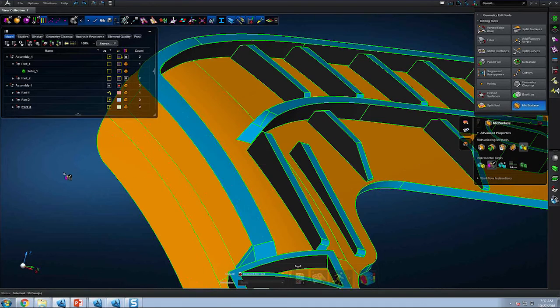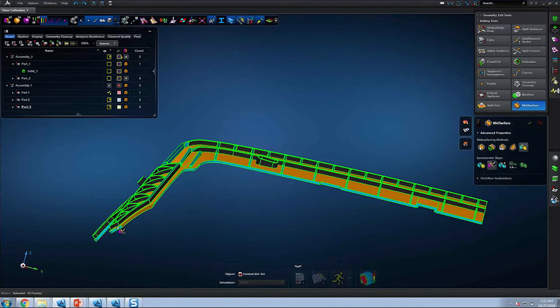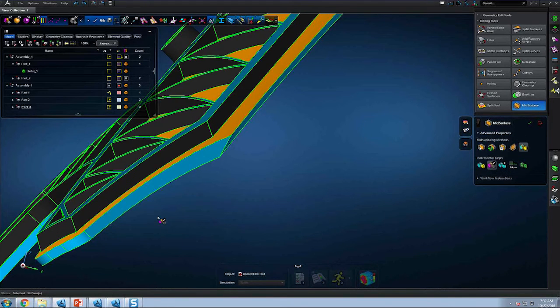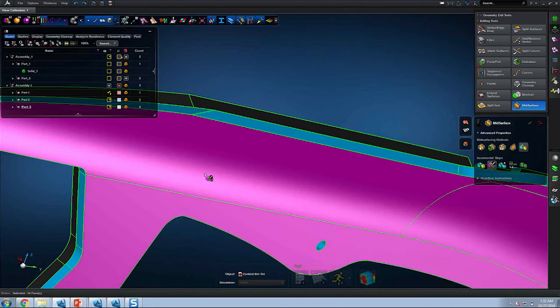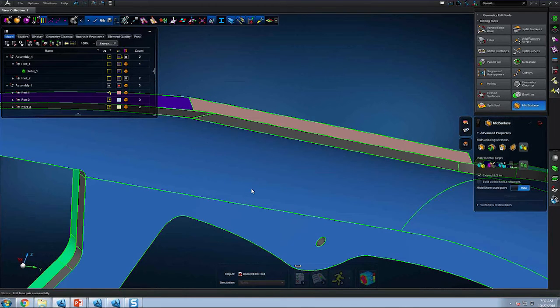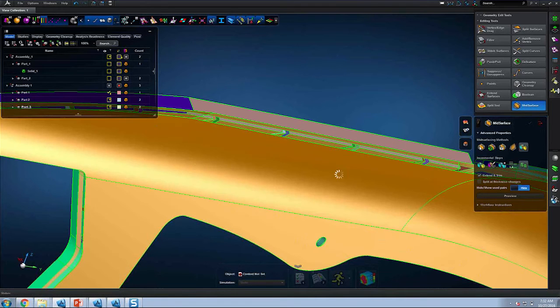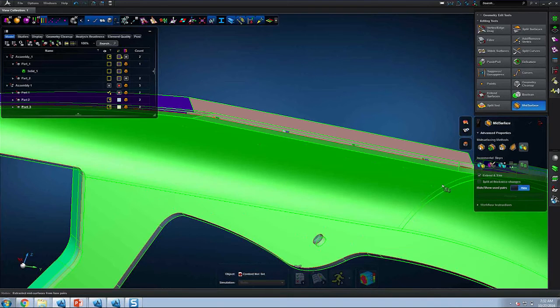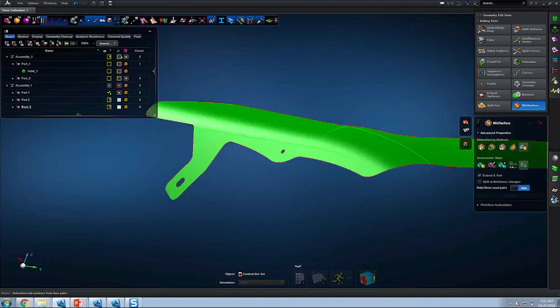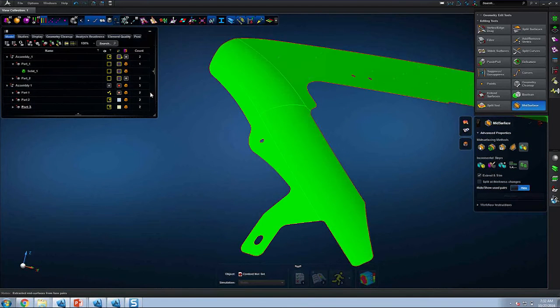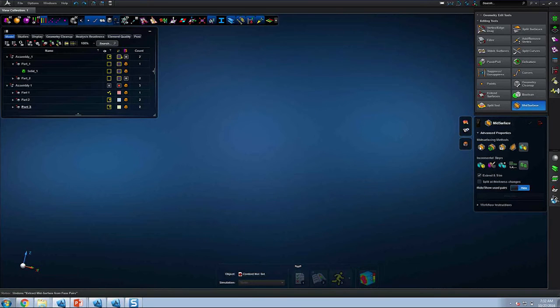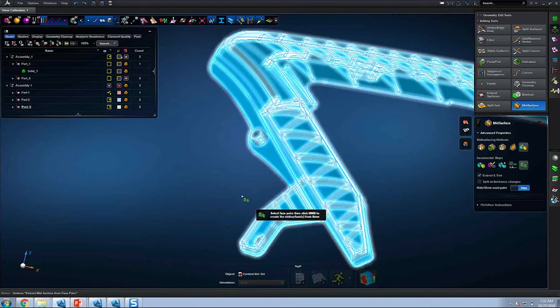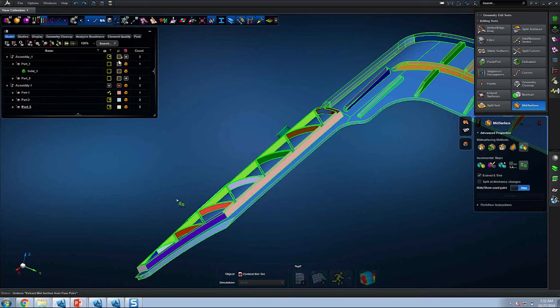And here's another face too. And I believe there is another one here too. What you want is for these pairs or faces to be really on opposing ends of each other. So now after the modification, after I go back and extract the midsurface for this pair, you'll find that additional midsurface that was just hanging out in space is no longer there. Now this is good for us. This is getting us closer and closer to a point where we can just connect all the midsurfaces together and get our final result.